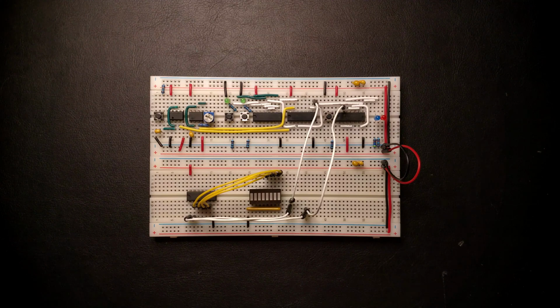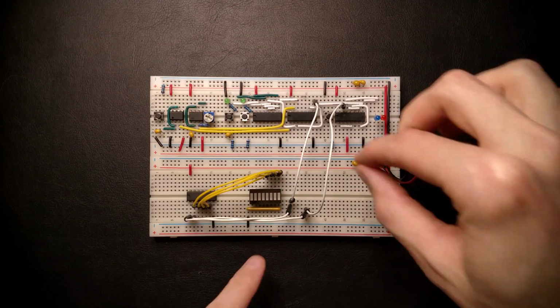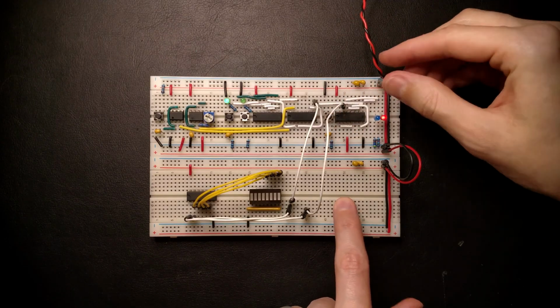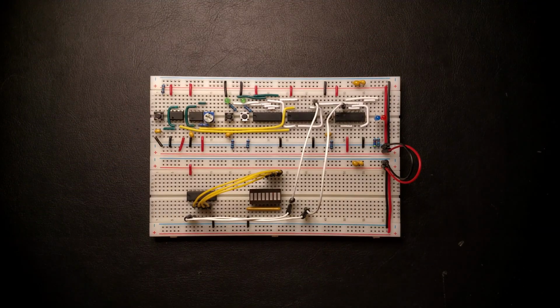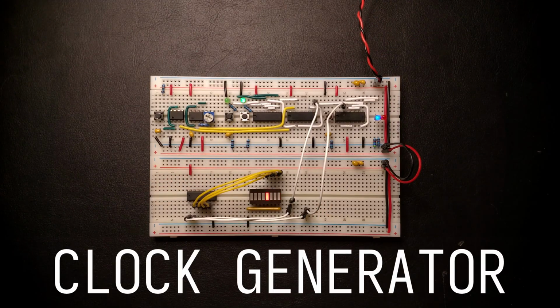I'm going to place a 10 nanofarad capacitor here across the step mode button and over here across the reset button. And now when we power the breadboard up a couple of times, it will reliably switch to step mode with the reset line activated. Great, this works like a charm. At this point, the clock generator breadboard here is pretty much complete and ready for use in the CPU.